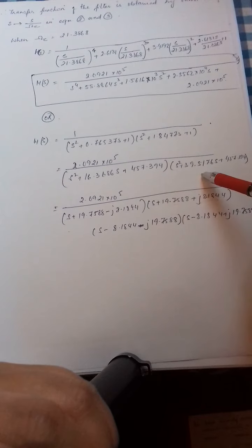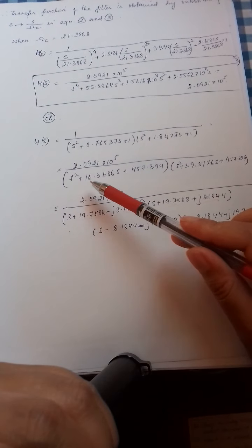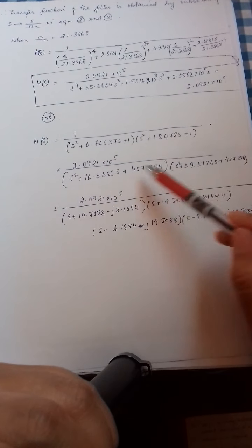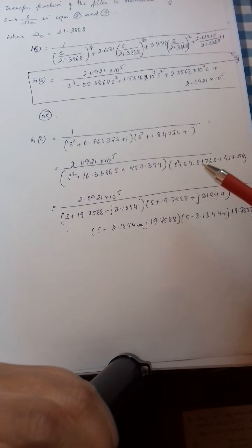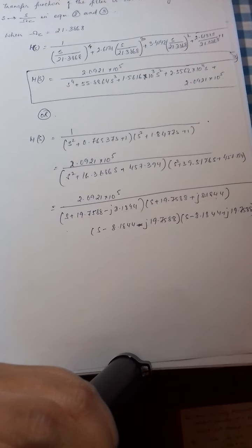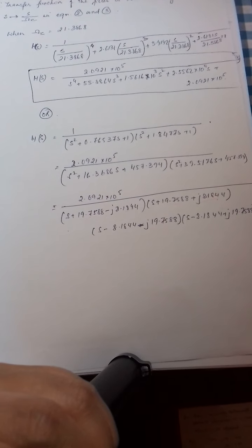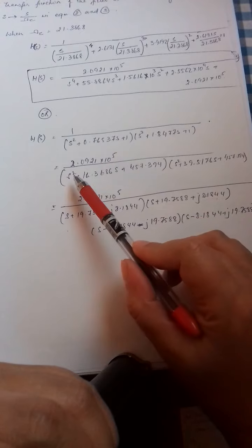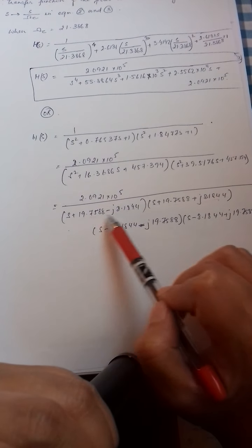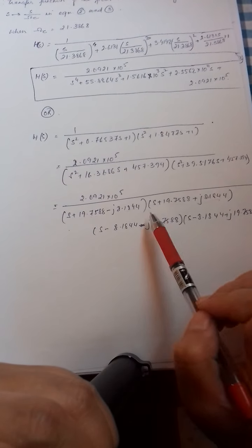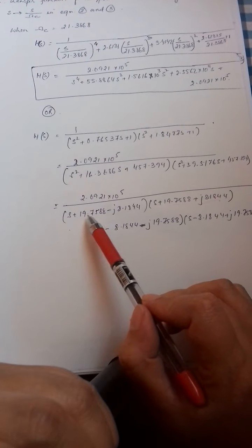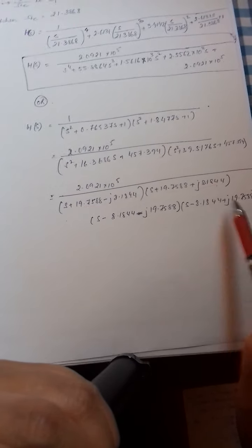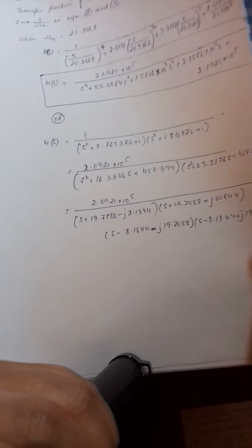So again, solve it, you'll get it in this form, and then you find the poles of this equation using that minus b plus minus root of b square minus 4ac divided by 2a. Using that, you will get these poles. Okay, so since it's a fourth order equation, you'll have 4 poles, 1 2 3 and 4. Okay, keep this also.